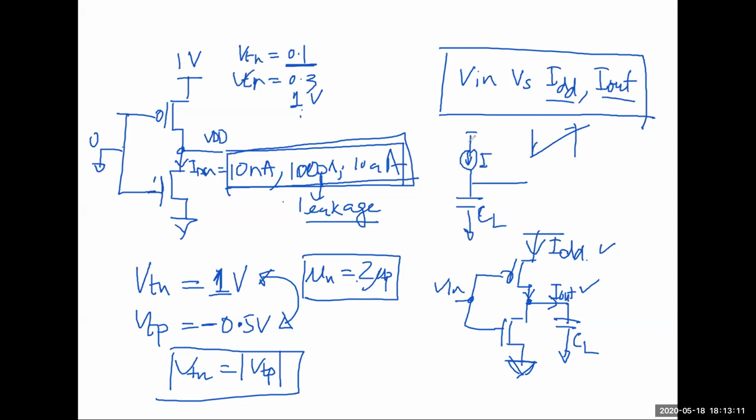Then you said, if it is in the linear region, can I treat it as a small resistor? Yes, if the voltage is really small, then it will look like that. And now you know how an RC responds. You know the final value, you know the initial value, so you can do that part like that. I don't care exactly how the equation looks, but the nature of the curve should be explainable from these types of approximations. I think that's what you're saying, Puneet. Yes, yes, sir.